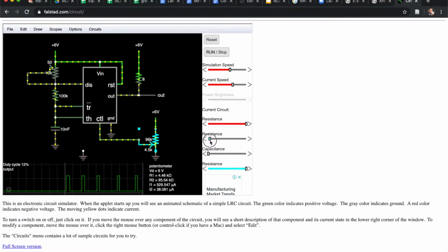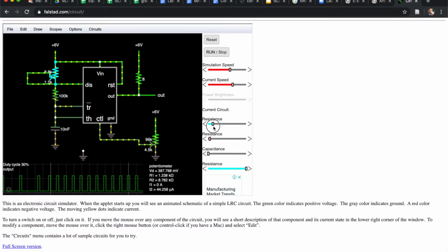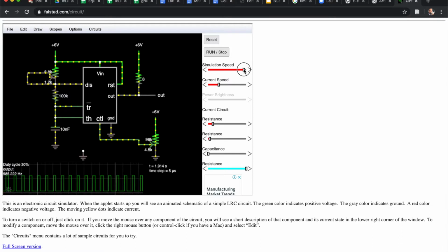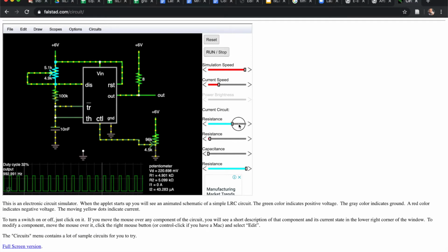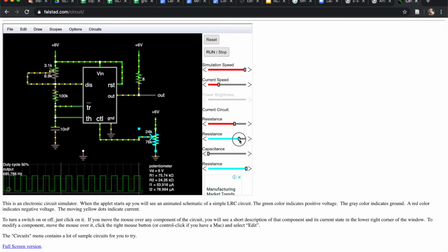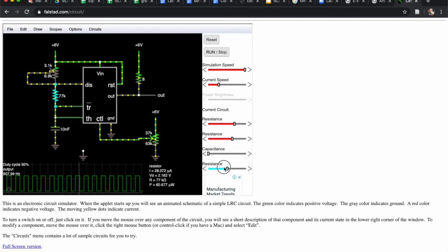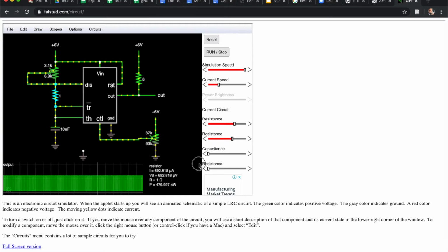There is a frequency estimation, so you will see somewhere in the range of maybe hundreds for very low values, and in the range of 10, 20 kilohertz as a maximum, and this happens to be coincident with the audio. So if we are smart about this, we are going to be able to see here the duty cycle, another term that you might want to research, and the frequency change when I move the sliders. So I expect to see that in the circuit and also to hear it.